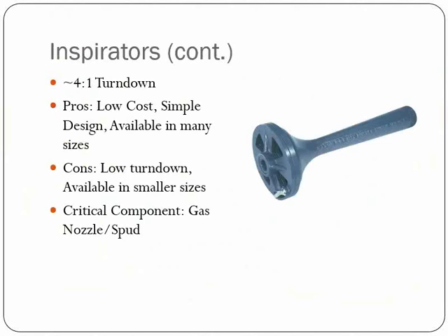There is no dynamic airflow adjustment. You have that shutter, which is fixed. So you put that in a position. You may fix that at a high fire condition, and then you turn that gas down as low as it can go to maintain the flame on the burner end of the inspirator.